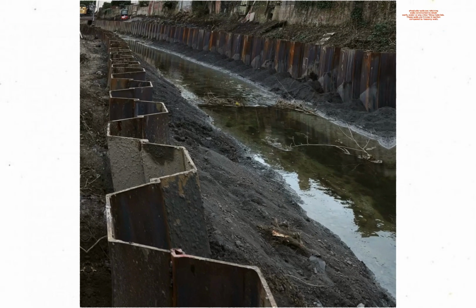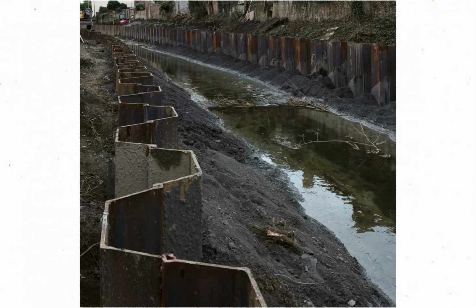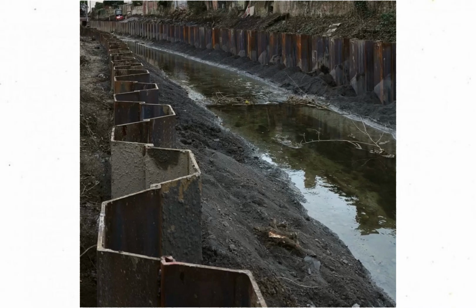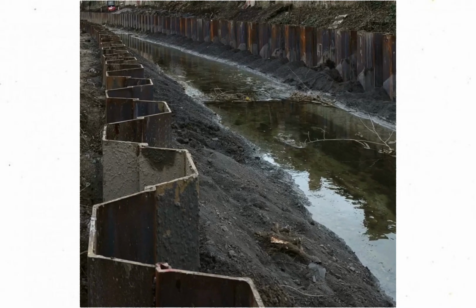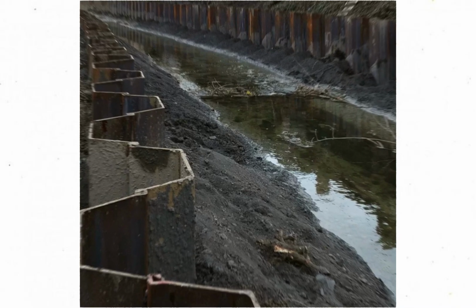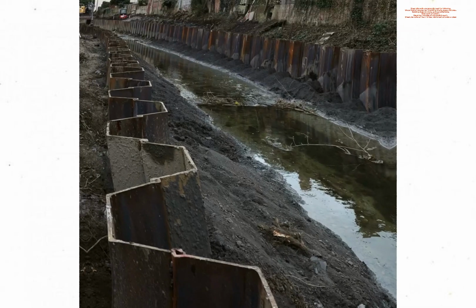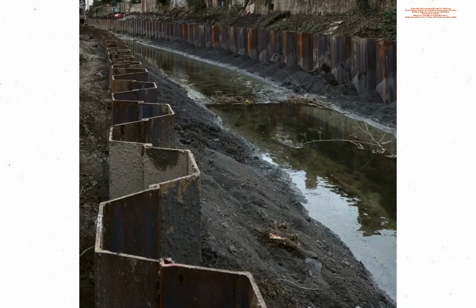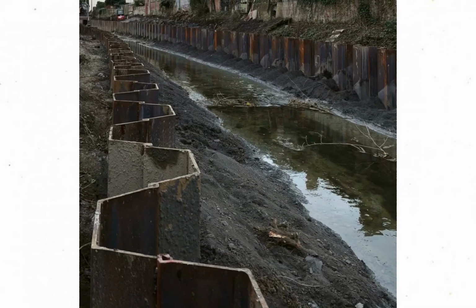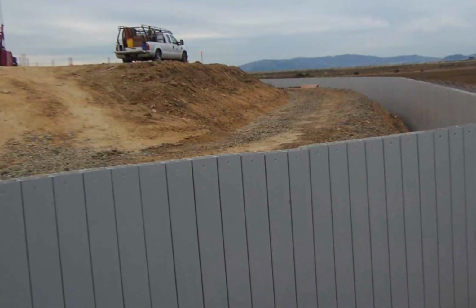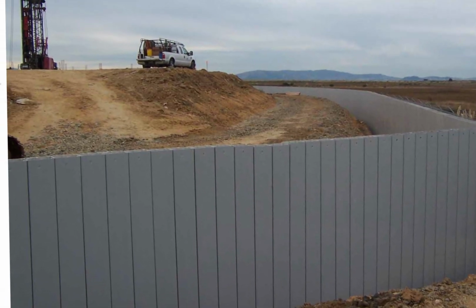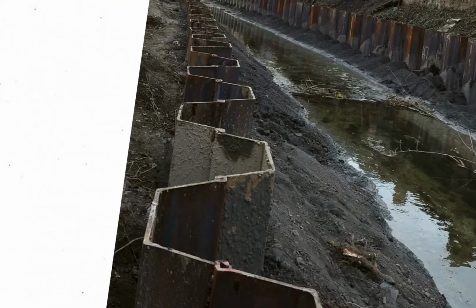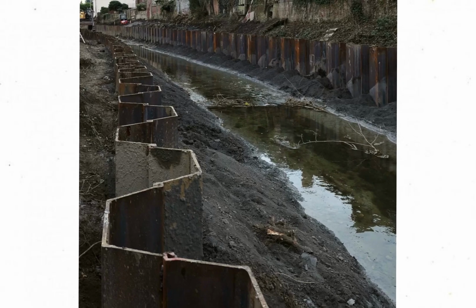Sheet pile walls are retaining walls constructed to retain earth, water, or any other filling materials. These walls are thinner in section compared to masonry walls. Sheet pile walls are generally used for the following: waterfront structures, that is, in building wharfs, quays, and piers, building diversion dams such as cofferdams, riverbank protection, retaining the sides of cuts made in earth. Sheet pile walls can be of timber, reinforced concrete, or steel.